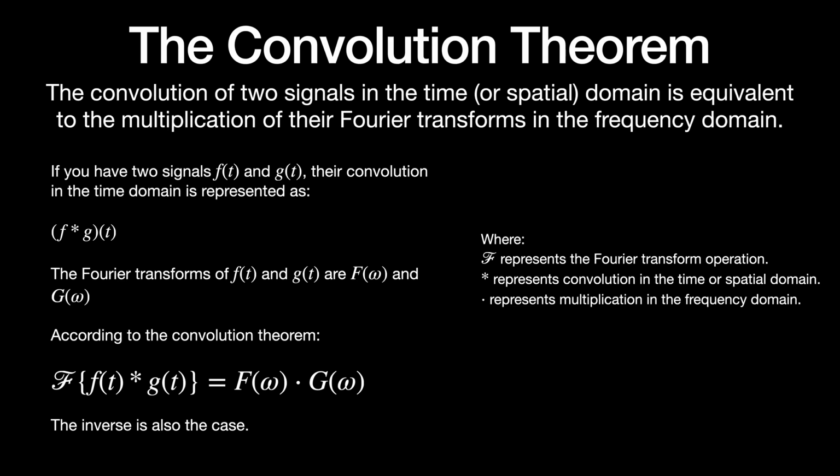If you've done any signal processing courses, you'll probably have been taught the convolution theorem. You really don't need to understand the proof or the maths, you just need to know that multiplying 2 signals together in the frequency domain is the same as doing a convolution in the time or spatial domain. So what we've been doing in the previous couple of examples was actually convolution.